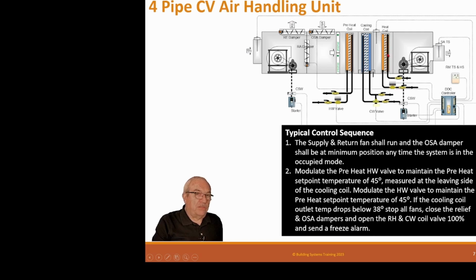So this heating coil doesn't need to be quite as big because it got one here. You do have to be careful that you don't freeze this coil up, so it has to have the right velocity and the right conditions in the coil to not freeze the actual coil up. So if we have pre-freeze coming in here, 30-degree air or something, this has to be big enough and have enough hot water in it to not allow that coil to freeze.